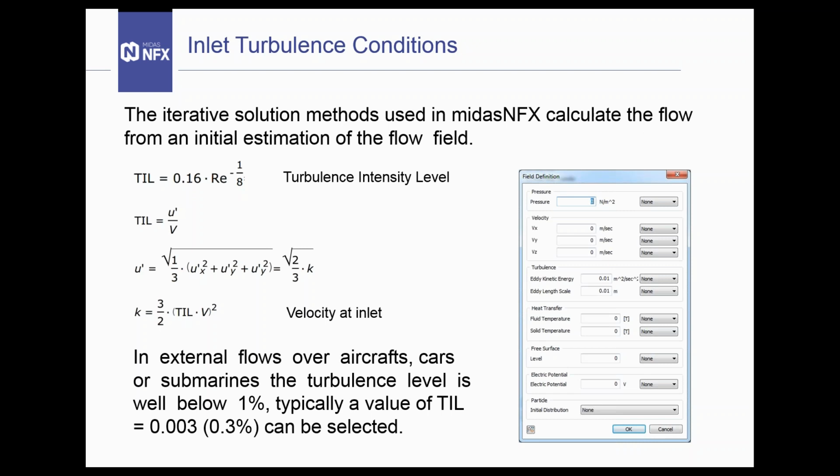So there is a need to estimate some quantities like the turbulent intensity level. In some codes you can define this with the inlet definition, but in midas NFX you have to simply go to the analysis case window and you can find the fields here, and the name is the field definition. So we are treating this as the initial condition.